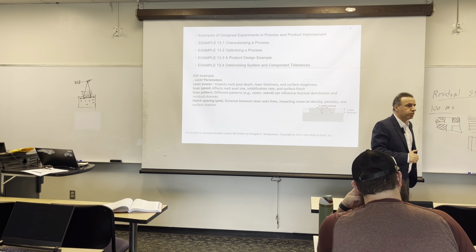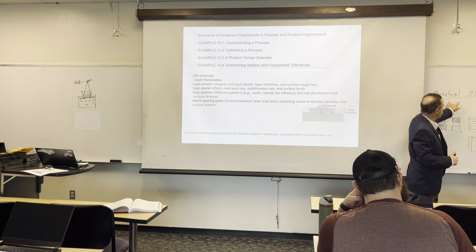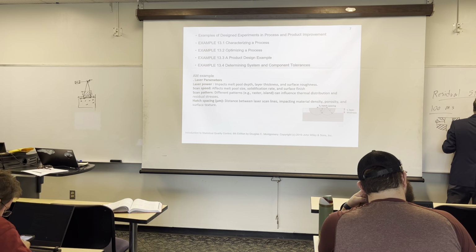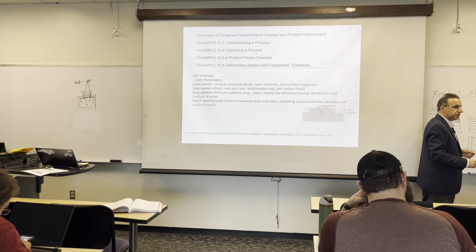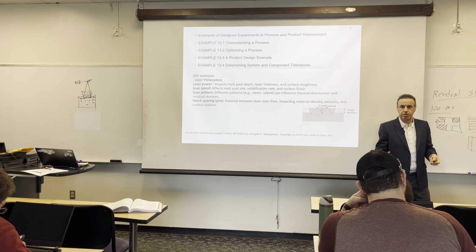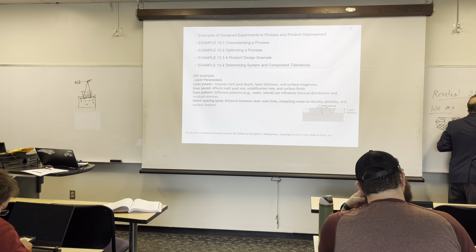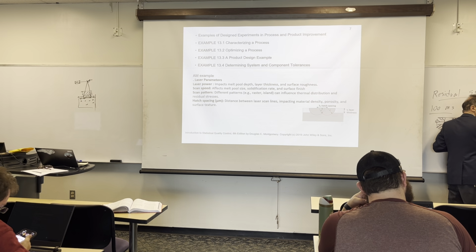But what happens if you have some residual stress? It means your part has some initial stress in there, somewhere here. And then how much stress you can apply before getting to this ultimate point, you're going to be left by this much. Let's say the total is 300 megapascal, right?